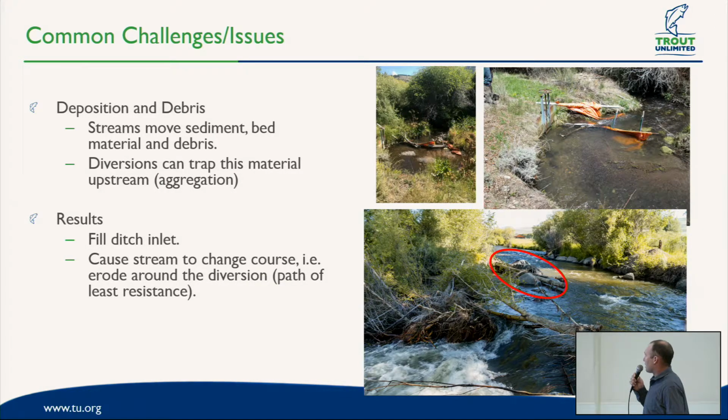The other issue that I think is real common, depending on the position of the head gate with the channel, is just getting debris, whether it be trees, branches, leaves, etc., that can seal up your actual head gate. And it's regular maintenance to get out there and remove those. There are some strategies to deal with that, more so with fine sediments. Trees and stuff are always going to be challenging.